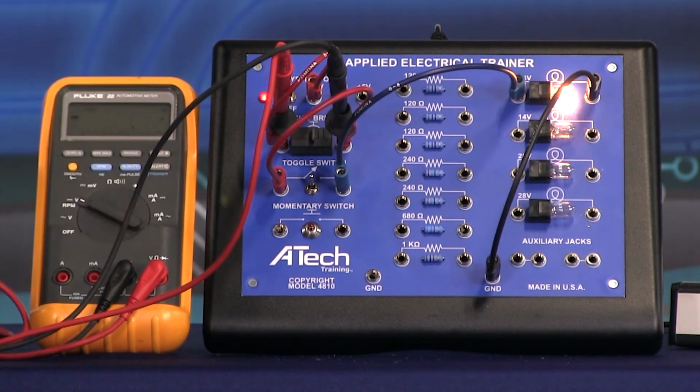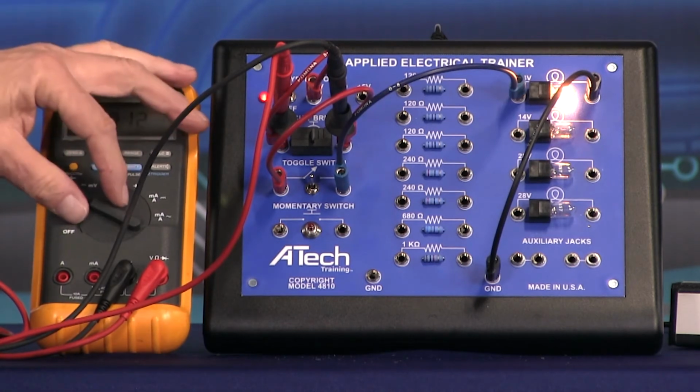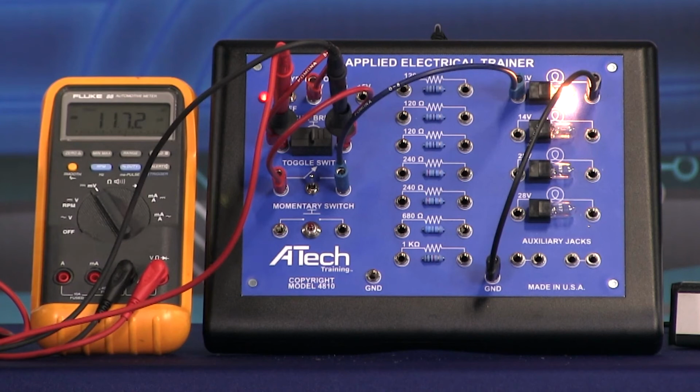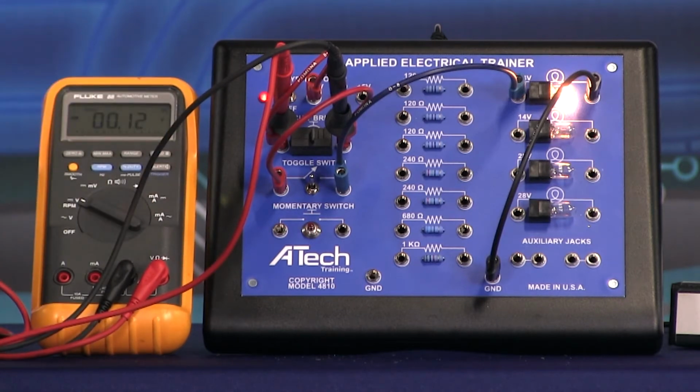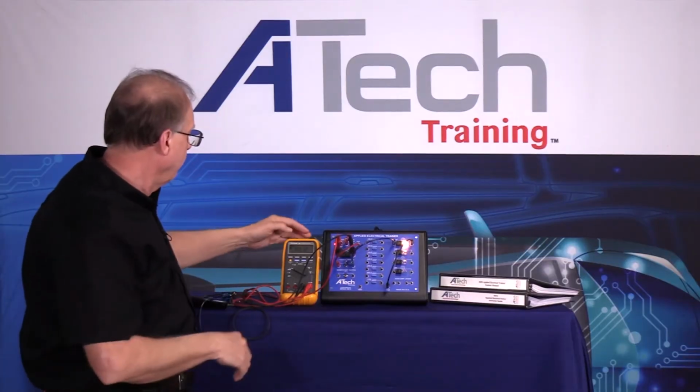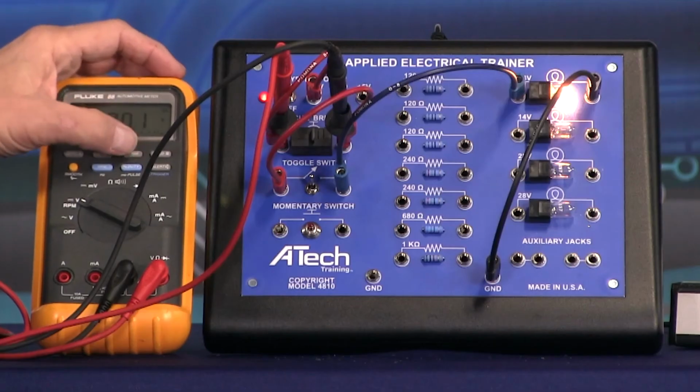Here's the deal. Again, this is something you're going to learn to use on your meters. It says 0.12, so I really want to know what the millivolts is, and it's 117.2. And if you look at that right there, it says millivolts. On this side, it says volts. So sometimes it's a good idea to adjust your meter. I also could come up over here and hit range.